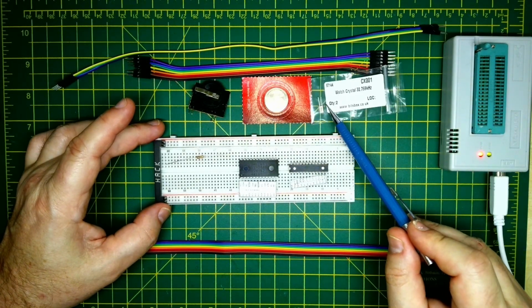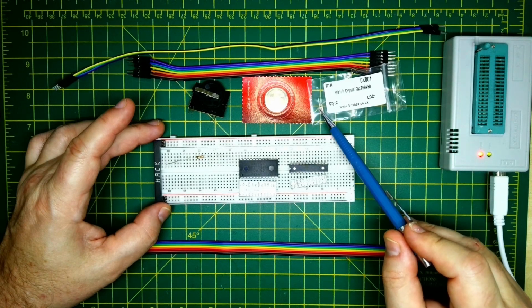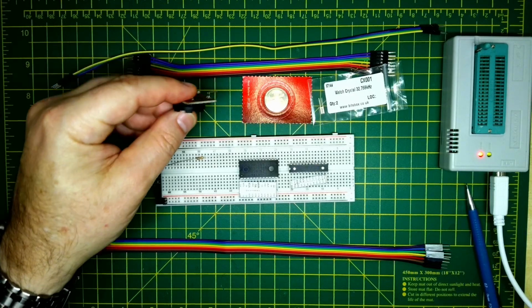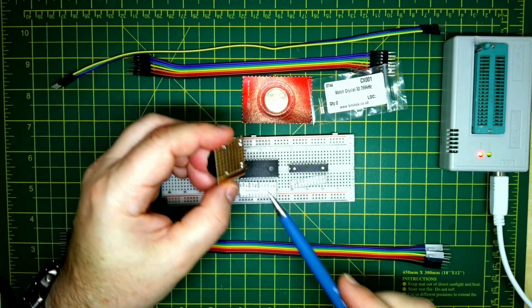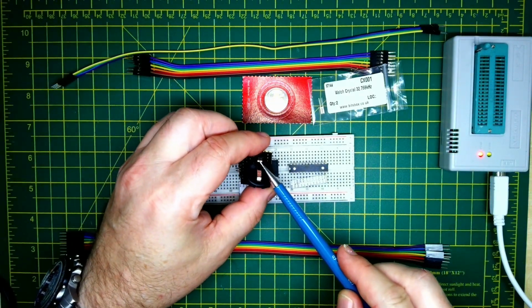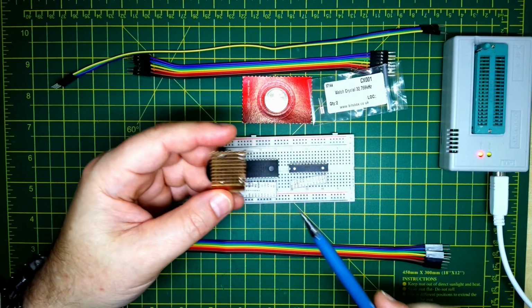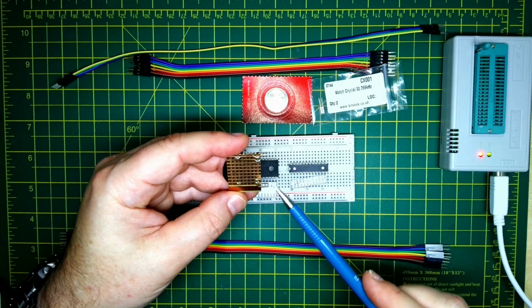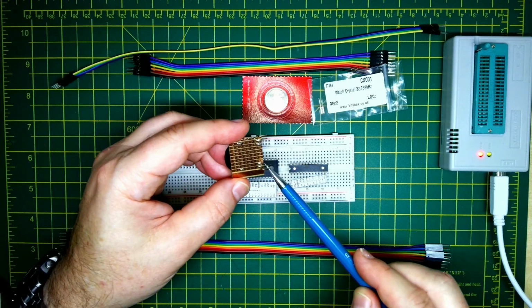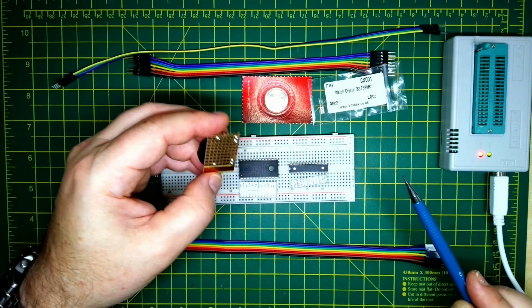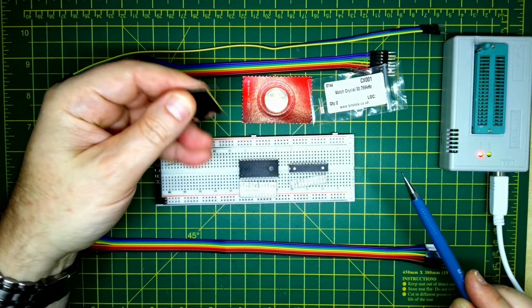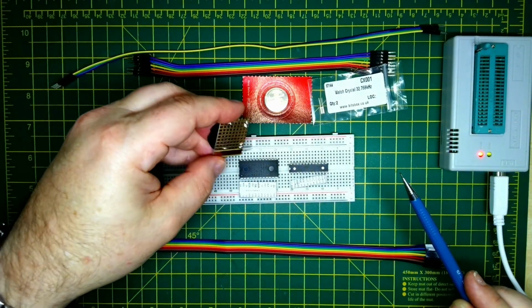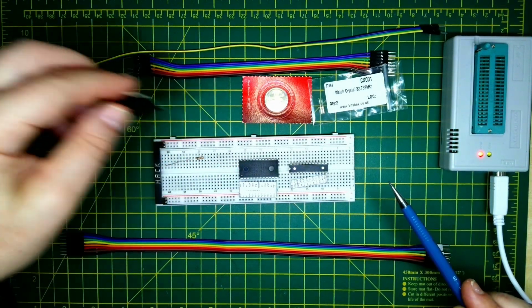I've got the watch crystals there, so they're very small, but hopefully those will go in one of the pins there. This is the button cell holder I've made. It's very simple. They're just positive on this side, negative on this side, and on the strip board only one of the pins on each side is actually connected. The other ones are just providing stability. The way this works should allow me to plug it in between the ground rail and the VBAT input.